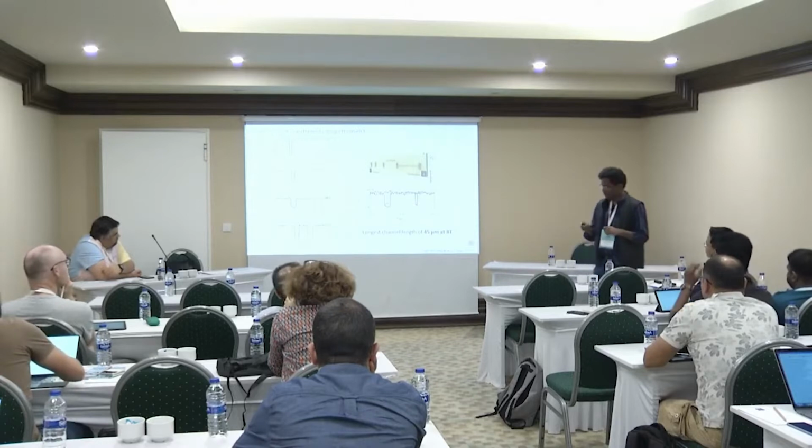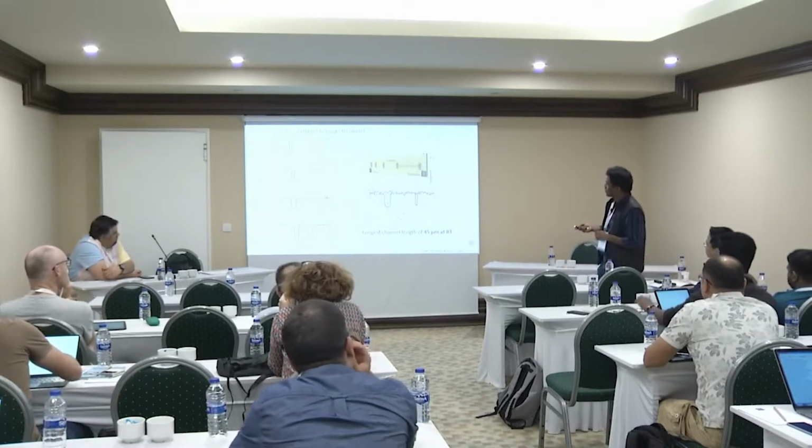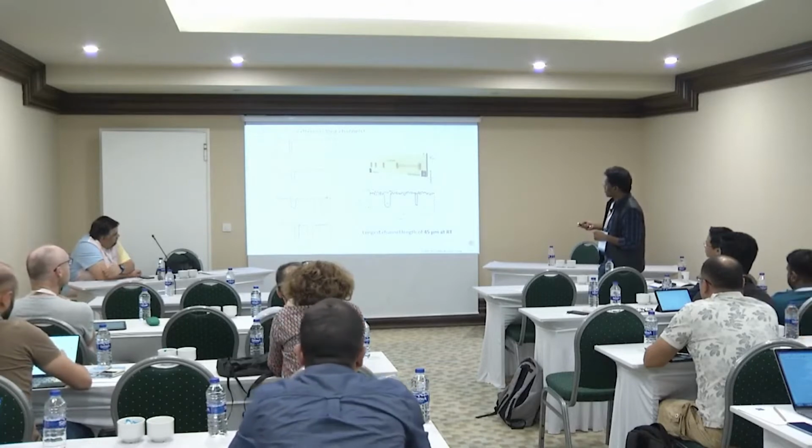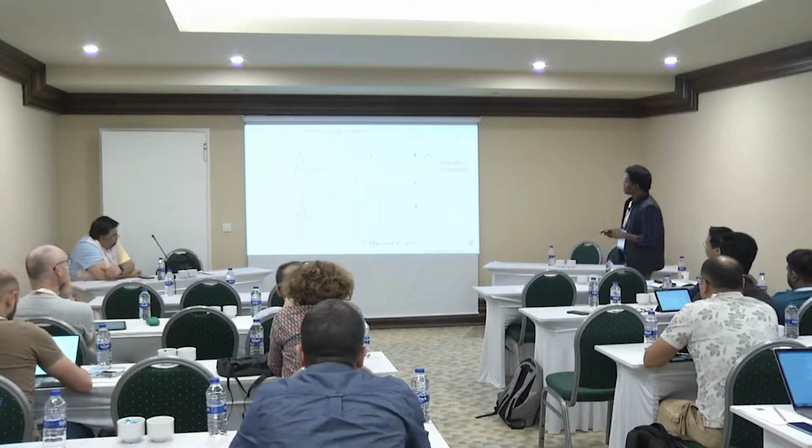one can get. So for the first time, you can see that this is a 10 micrometer, this is a 13 micrometer channel, this is a 51 micrometer channel, and this is a 36 micrometer channel, which is the longest channel in which spin signal was reliably, robustly observed. And we could go even up to 45 micrometers spin transport. We can clearly detect spin transport in these channels.